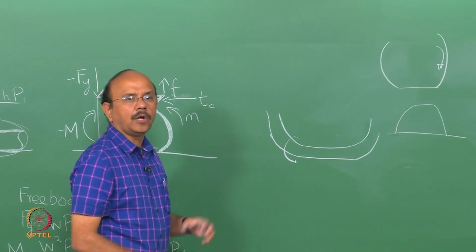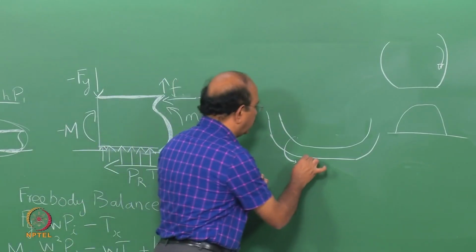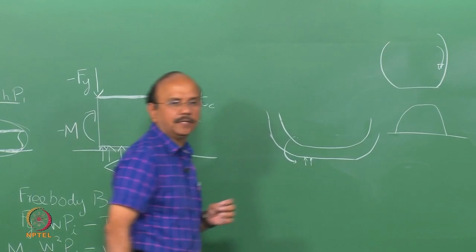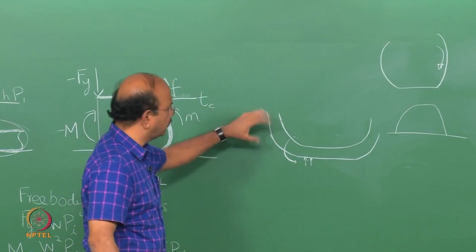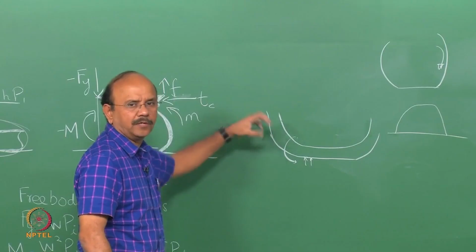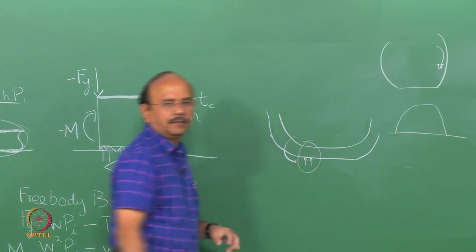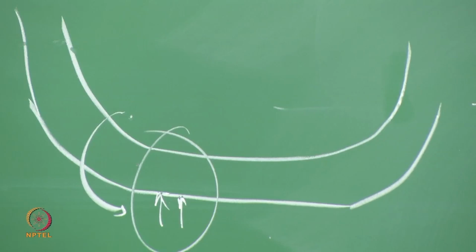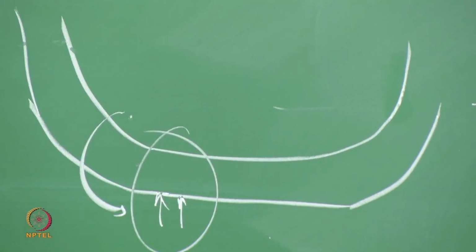So now what would happen because of that bending moment? There will be more reaction forces here. There will be a reaction force here. Depending upon who wins, there are a number of forces there. Who wins, there will be a reaction force at this edge. In other words, this bending is going to alter the contact pressure distribution.